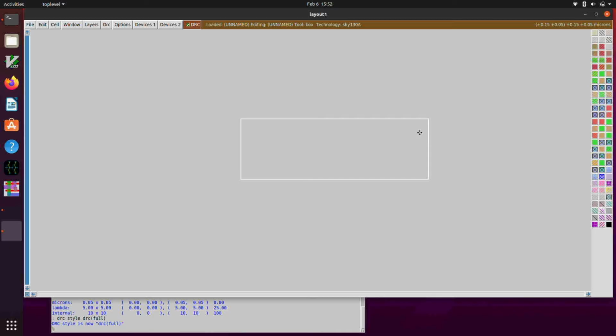But you can imagine that for a very complicated layout, maybe when we're looking at the whole chip or something like that, having it check all of the design rules on all of the geometry that's present could slow things down quite a lot. And so they have reduced design rule sets that can be enabled that, for instance, if we're doing routing, we might not want to check for design rule violations on all the geometry that's not changing.